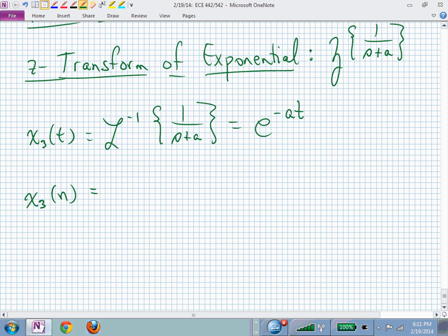We now want to find a sampled form of that, so that now we have this e to the minus at with t, little t, replaced with little n, capital T. That's all we're doing when we're sampling, which says that we now have e to the minus a n T, right? A way to remember that. So we now have an anT somewhere. Got it. And we're trying to z-transform it. Ooh, it's going to get messy, isn't it?